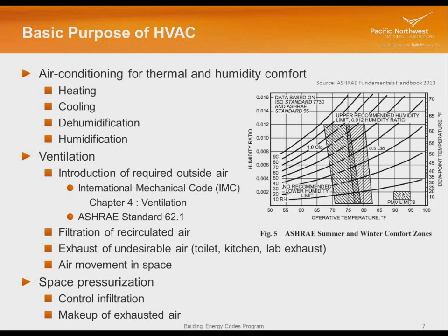Space pressurization may also be part of the HVAC system purpose. In other words, keeping a positive pressure. This is more typical in commercial buildings, so that you keep infiltration out during the occupied hours, and also making up exhaust air. So if you have a lot of exhaust air, you need to make sure that you're bringing in outside air in equal volume, so that you aren't having the front door get sucked in to provide makeup air back into, say, the kitchen.